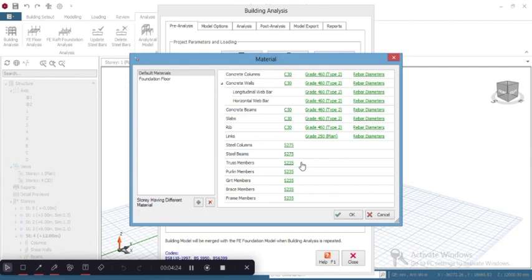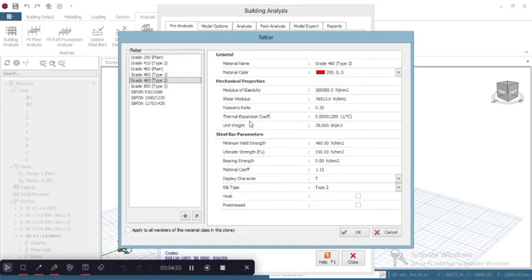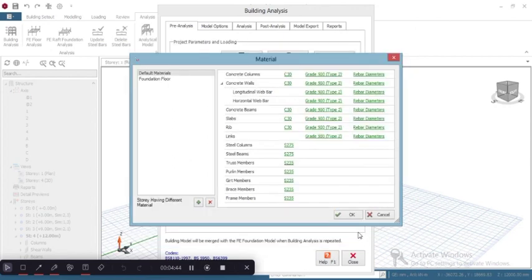So running C30. Pick steel grade and ensure that it's grade 500. The 500 is what we use. You can apply to all members also. Click OK. Now pick diameter and select the desired rebar diameter to be used in the member design.